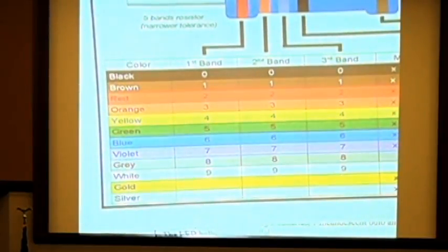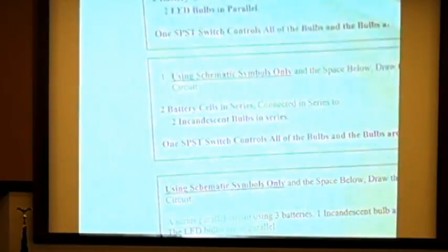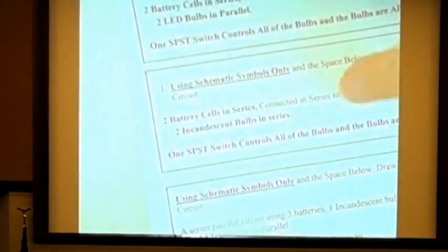Okay? So do they add the first 2 bands, or is it? No. No. It's a 2-digit number, 43, 55, 76, and then some zeros following. Okay? So it's the first number, the second number, and then the zeros. Okay? All right. I hope that helps you out.